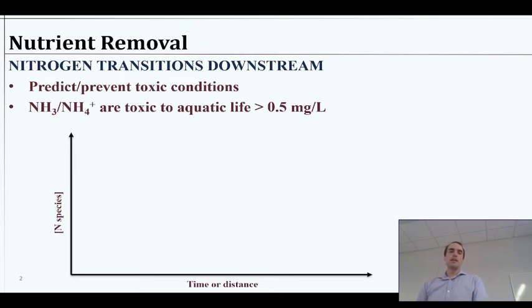So the nutrient, the nitrogen in particular, the nitrogen cycle, is quite important because ammonia is toxic to aquatic life at pretty low levels. So if you've got 0.5 milligram per liter or more, you're starting to get in a range where you've got some significant toxicity. So what happens in a brand new aquarium? There's not really a whole lot of bacteria around. You've got oxygenation, all this happening, and you put a fish in there and you're excited, and you're trying to make sure it's happy, so you give it a lot of food.